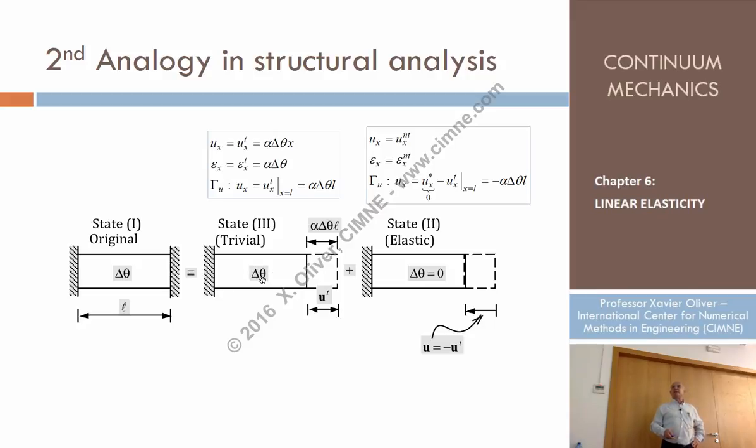If the temperature is delta T, then alpha is the expansion coefficient. So how is the beam, the cantilever, expanding? We know that the thermal strain would be alpha delta theta. So the expansion would produce a displacement field that is alpha delta theta times x, and specifically at this end, the displacement will be alpha delta theta times L. Okay? And then what did you do?